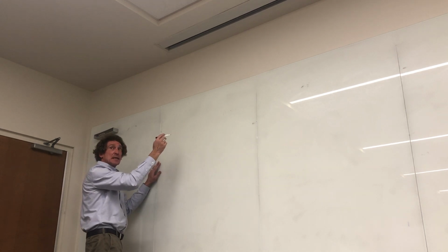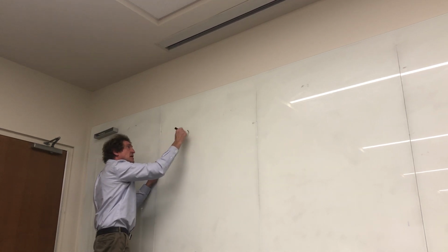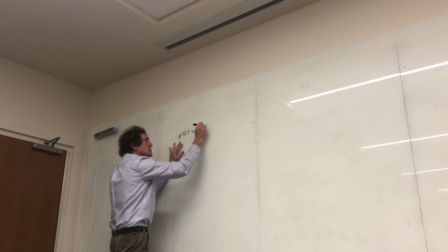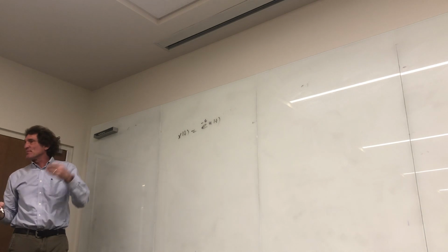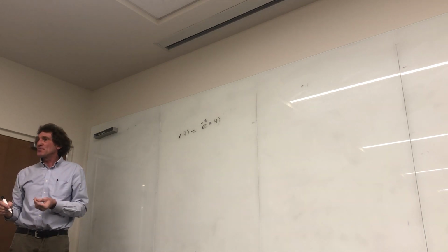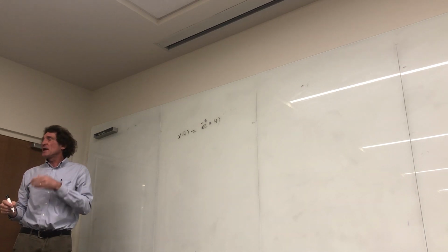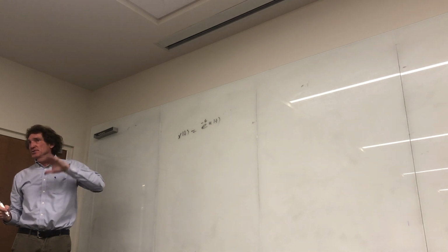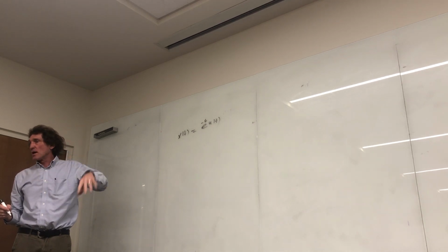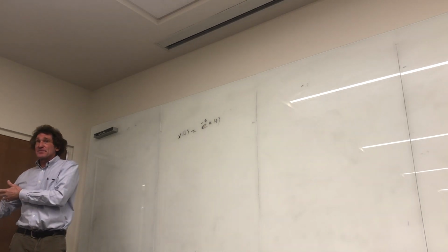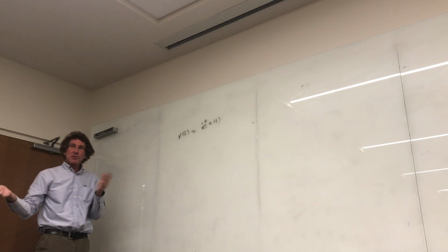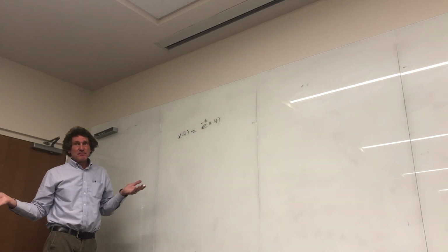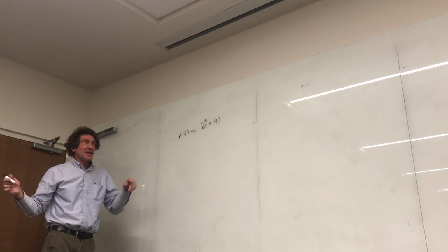So the next thing is this. We're going to let x of t, the input to the system, be equal to e to the minus t u of t. Now you might as well just do this in the Laplace domain. There's no reason to do it in Fourier. I will never confine you to do it just with Fourier or just with Laplace. You've got to understand, you can't use Laplace when it has values that are non-zero for t less than 0, so that automatically disqualifies it. If you did, you'd really have failed miserably.